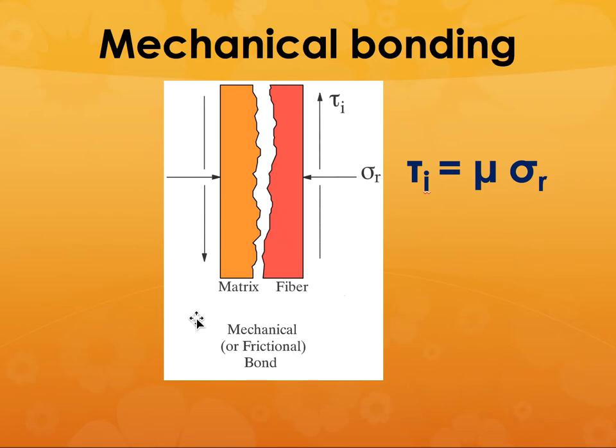So it creates some kind of excess frictional bonding between the matrix and the fibers. So when you are trying to mechanically load the composite, those frictional bonds have to be overcome in order for the composite to fracture and to break. So that gives you better mechanical properties and therefore is a good thing to have.